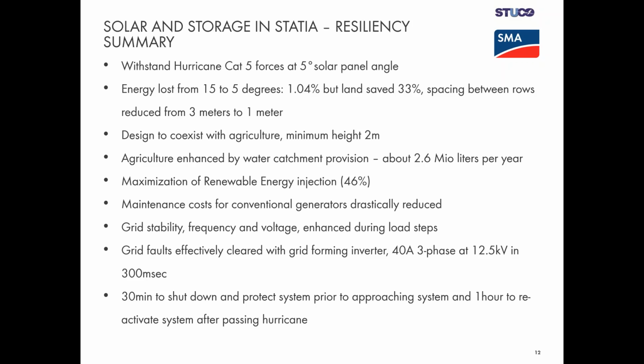The energy loss, certainly some of you may be wondering about that, or how much energy we lost. It was only when we reviewed the calculations before deciding to space the panels closer. The calculations indicate only a loss of 1.04% of energy. But the land that we were able to save for expansion was 33%, as the spacing between rows was reduced from 3 meters to 1 meter.